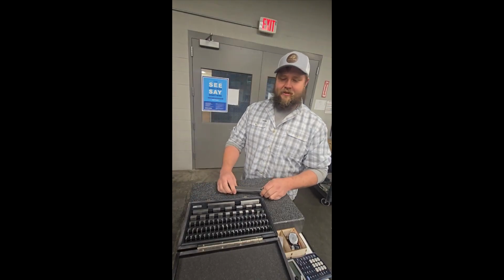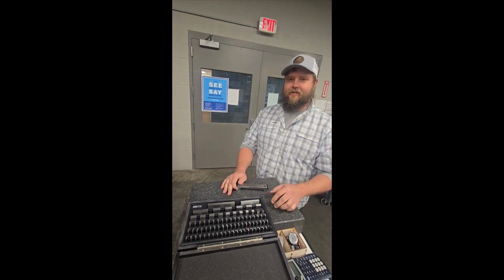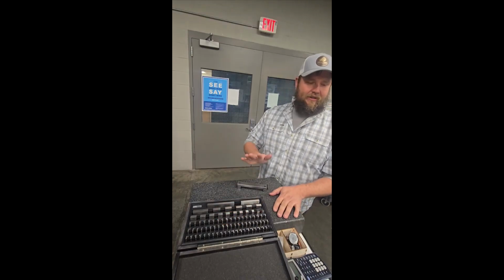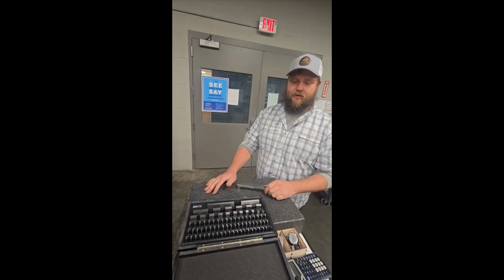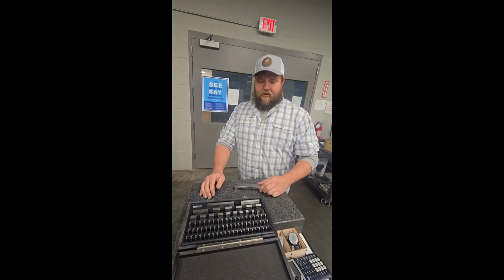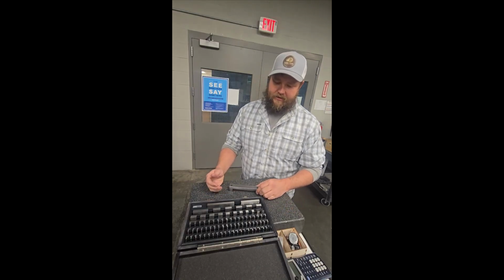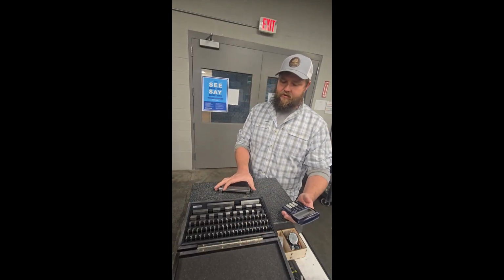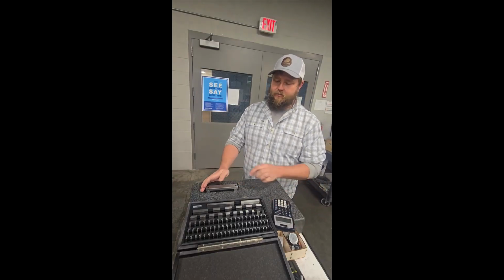So, I'm Jared Venata. I'm going to go over some of the fundamentals of metrology here with the surface plate, gauge blocks, and we're going to use a sine bar as an example of the two coming together. So, to measure angles, if you want to get within about 1/100th of a degree, you can use gauge blocks, and this is called the sine bar because it's 5 inches from cylinder to cylinder, so we can calculate our angles between it.